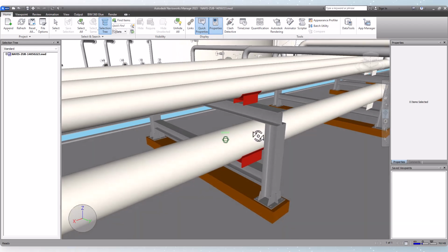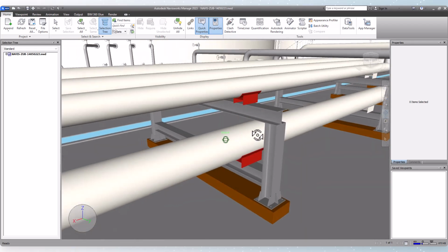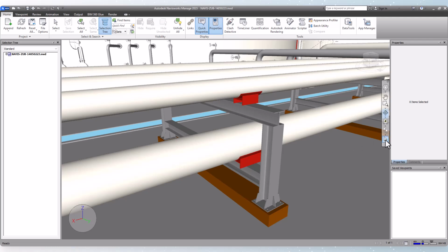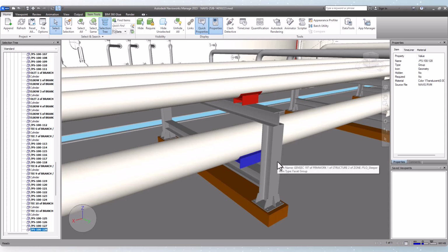Pipe support modeling has always been one of the biggest challenges for AVEVA E3D and PDMS designers. One approach is to use the support module. However, because it often produces errors and can be difficult to manage, many designers prefer not to rely on it. A more popular and practical solution is to create pipe supports as attachments. This method is easier to manage, more reliable, and integrates seamlessly into the piping model.